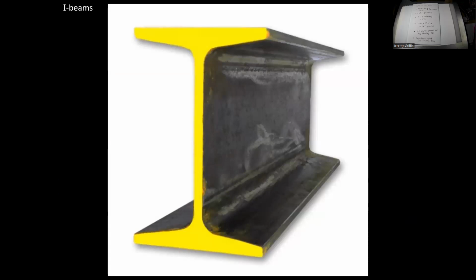And since most of the tension and compression happens in these top and bottom flanges, that's what these are called, by the way, flanges. Well, that's where you want most of the material, right? That'll carry most of the stresses. And if this is embedded in, say, concrete or surrounded by concrete or some other material, it also provides an economic solution, right? Which again, it's like the other half of this. You have to think, well, somebody's paying for this project, because steel is much more expensive than concrete. So, you know, if you can just have the steel exactly where you need it, then it'll help minimize cost too.